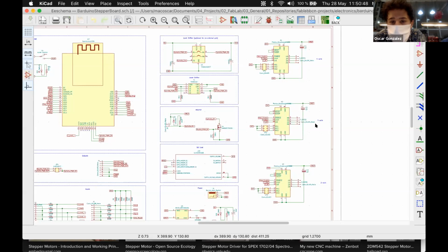there would be a need for another stepper driver if you wanted to make this as a 3D printer, and you will have a little hard time if you want to keep the same amount of pins in here with the Arduino. But I encourage you to make either an external driver controller or reduce the number of pins that you use for inputs or outputs, and then put another stepper driver controller if you want to. At this very moment, we are limited to 3.